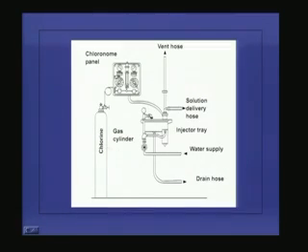So, this is another chlorination panel. Another method here: an injection tray is there and a vent hose is there, and this is the water coming. It will come here and mix with the chlorine, and the mixed chlorine solution comes out and goes to the tank meant for disinfection, and this is the gas generated. Okay. So, we can vent it through this hose.